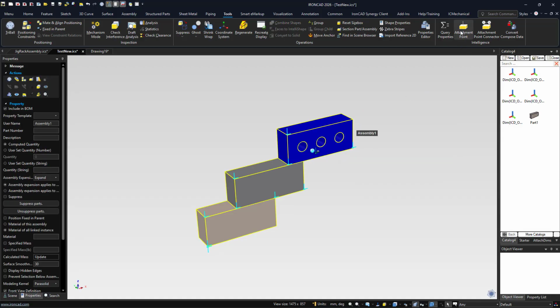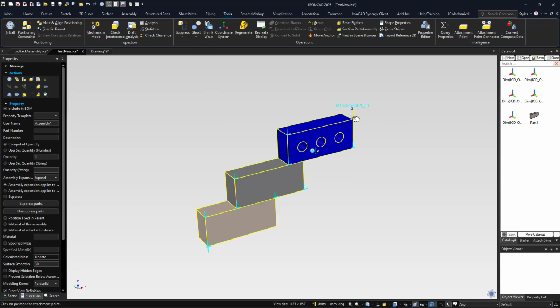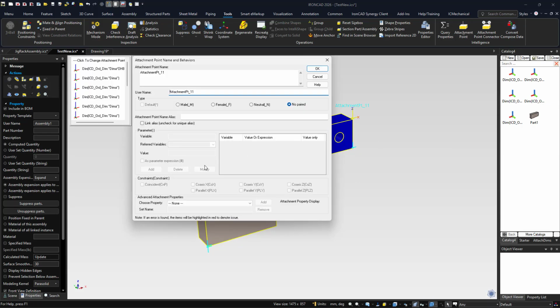Put one here on the assembly level on the top right. And what we're going to do is go into the names, and we're going to go down to our ICD catalog item in this case. So this one's a little bit different, and I'm going to call it CT, and we're going to hit add. So that's all it takes for those. So that's the name that it's looking for in the catalog. You have to have an open catalog in the drawing that has that component name CT. So that's what it's looking for in the drawing to call that.